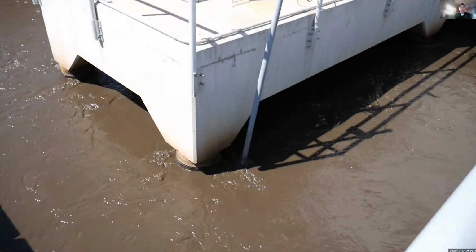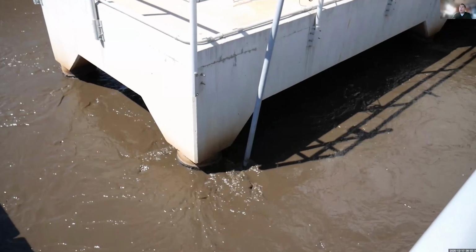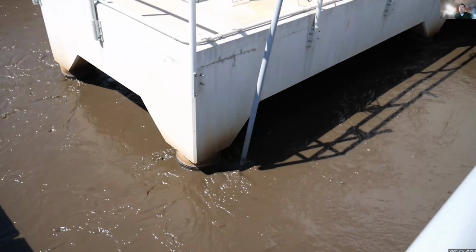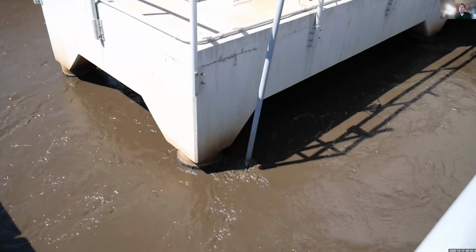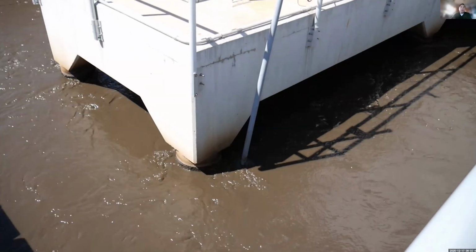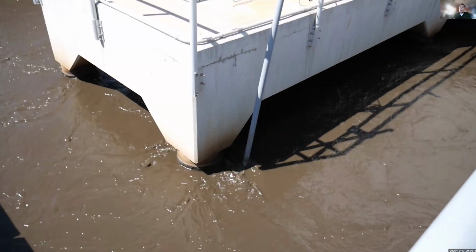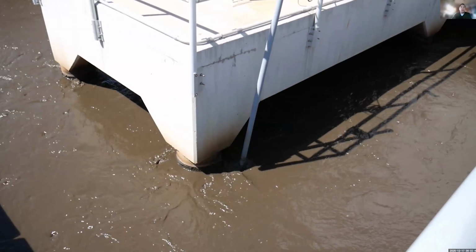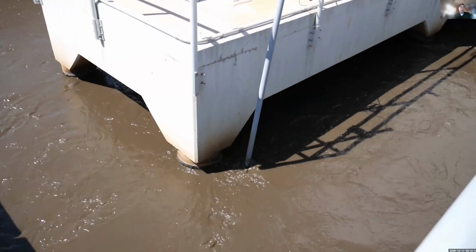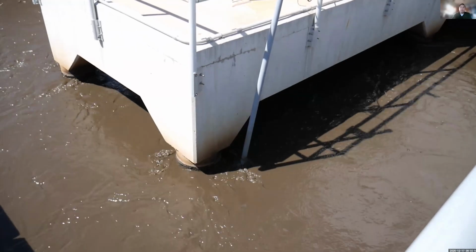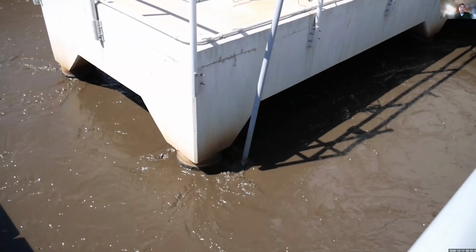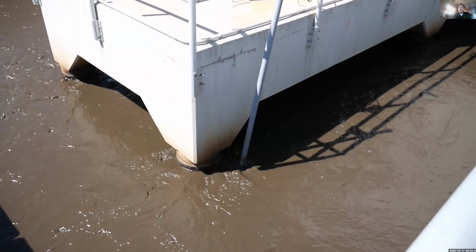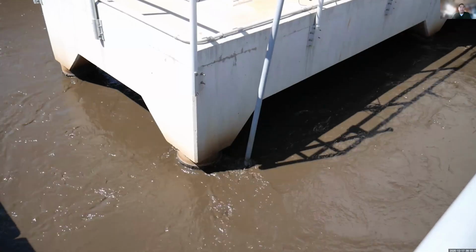So here we're just showing an example of some mixing, showing how to make sure that our organisms and our biomass and our MLSS are always being mixed correctly and what that should look like, to make sure that they're able to form flocs correctly and that the interactions between the nutrients and our biomass are being carried out correctly. And then in this example, we'd also probably have decent nitrate removal if that is one of the permit requirements of our plant.